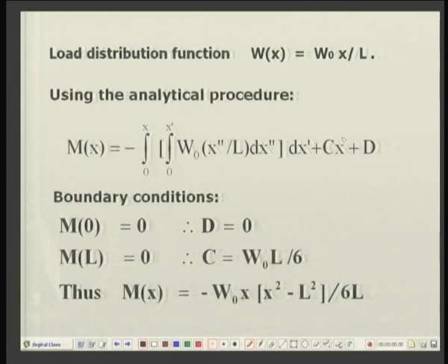So, W0 x divided by L. Now, the formulas which we have already derived connecting Mx, that is the bending moment distribution, with the loading distribution. So, this is direct substitution of the formula. The loading function Wx is replaced by W0 x divided by L.